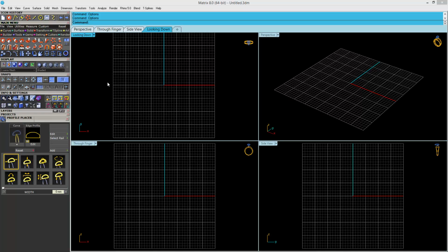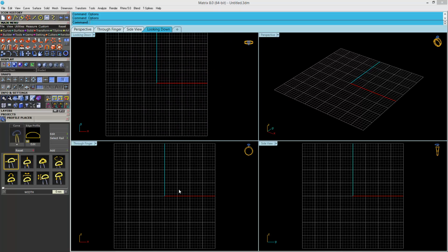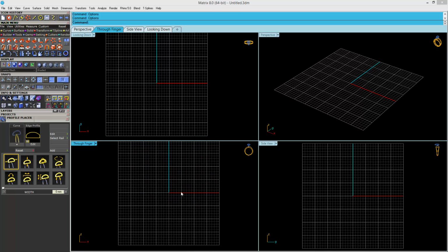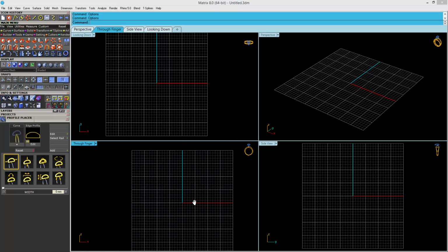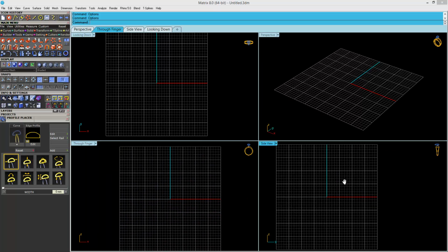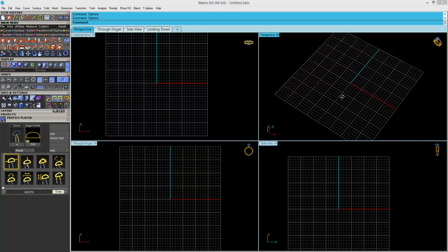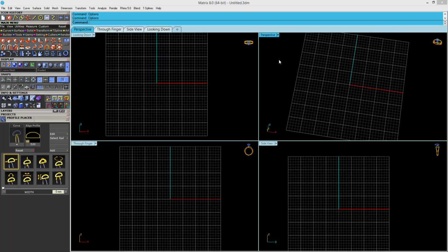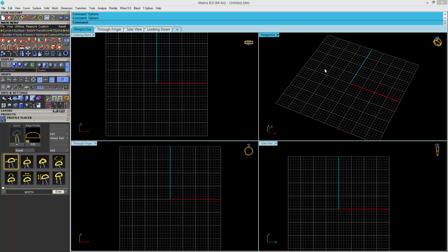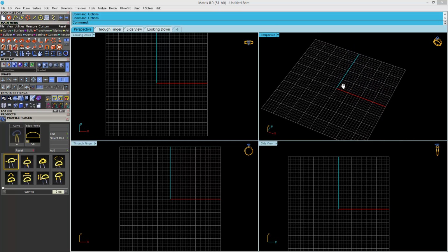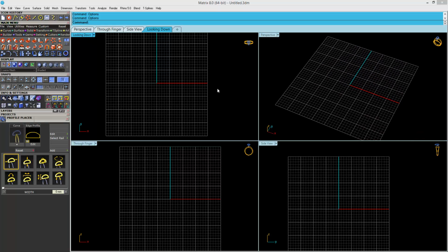Wait a minute. Where was I? Yes, you can pan the view by right clicking on it, on all of these 3 views. So what is pan? Pan is to adjust the screen, to bring it left, right, up, down. The same thing here, but you cannot pan here with the same technique, it will rotate, because this is specialized to see your 3D models. If you need to pan, you need to press shift, and then you can pan it.